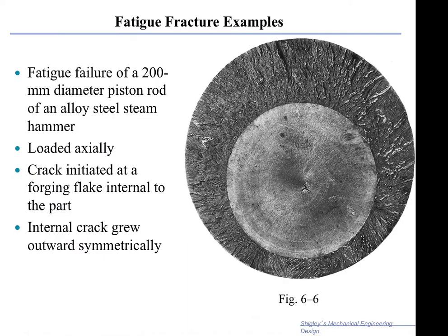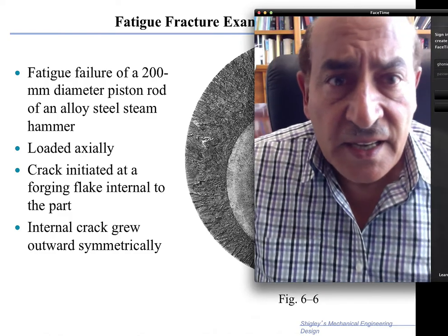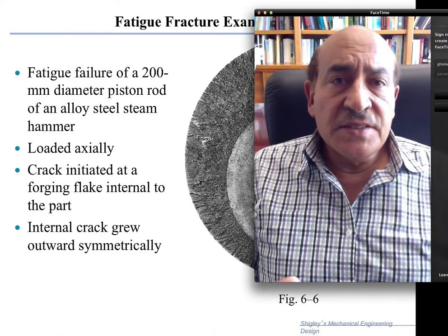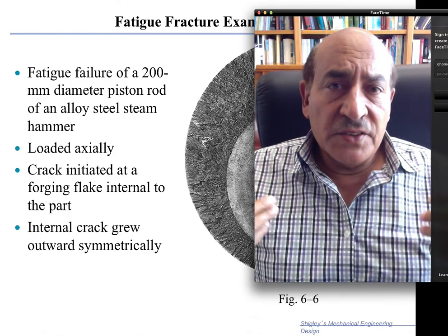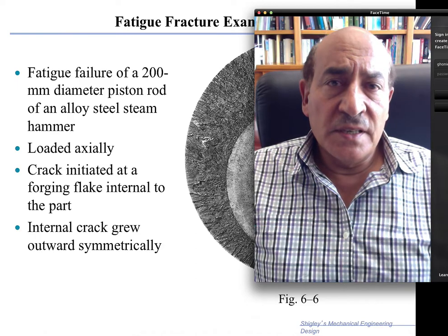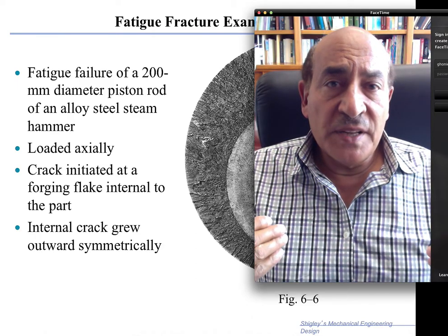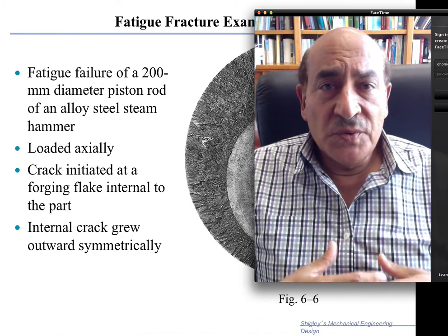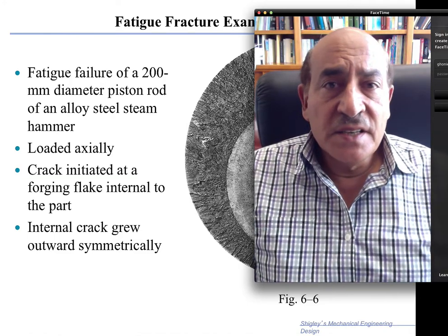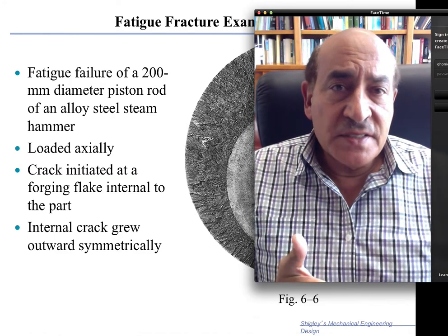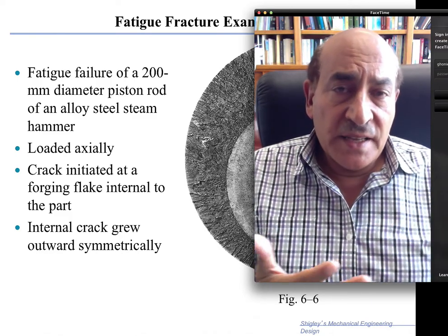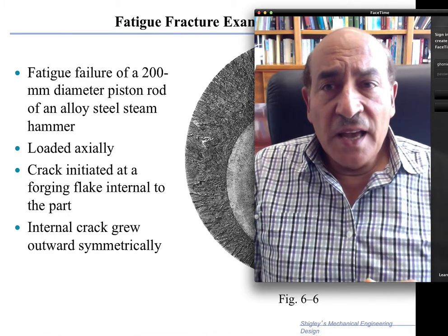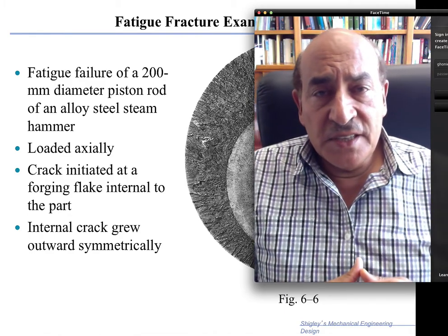Next is an example of fatigue failure, which I find interesting, because as you've seen in most of the other failures in the previous examples, the crack is initiated always at the surface. Not only that, but at a discontinuity. So we would think, okay, if we're designers, we just have to go after these discontinuities and put fillets and round them and grind them and smooth the surface, and here we go, we avoid the fatigue failure.